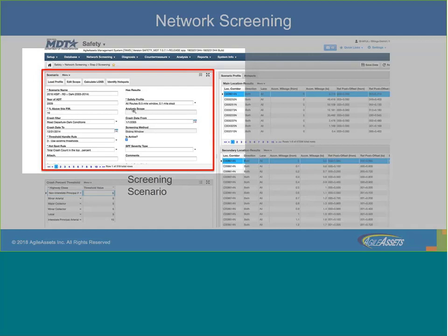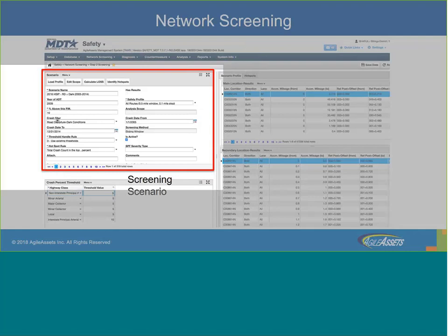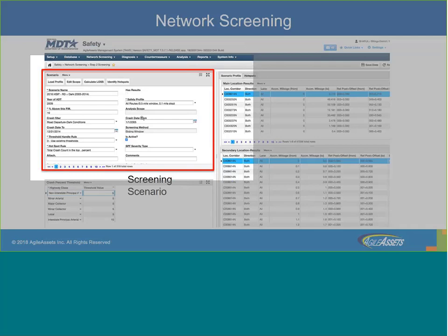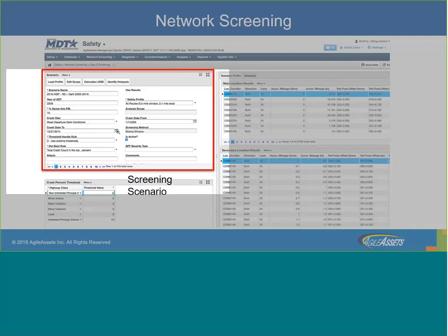So for the safety profile, you basically identify the profile that you are considering. Then you have the selection of other parameters, like what crash filter you are using, so distracted driving or roadway departures, you use those filters. You specify your crash date, which is date from and to, what is your analysis period. And you also have some techniques like what will be your hotspot selection criteria. So you can consider, okay, my hotspot will be like, say, top 95th percentile or top 90th percentile. That hotspot selection criteria you need to provide in the hotspot rule.